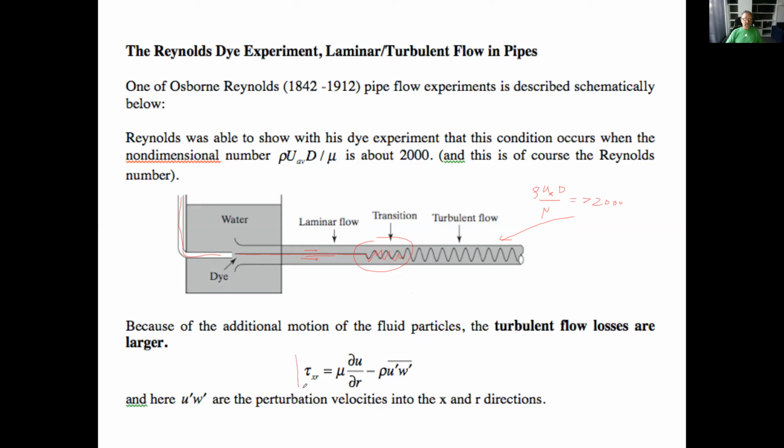Here's an explanation, which is, again, I'm just showing it to you so you'll have a clue. We claim that this is the term, the shear term. But in shear, the turbulent flow, there is actually velocity of the transport, of the fluctuation of the velocity back and forth, and to the side as well. And that is some kind of represents the momentum loss due to this side motion as the fluid moves along in the pipe. And that has to be included in the friction. And experimentally, that explains why the friction coefficient, if in this case here versus this case, is significantly larger.